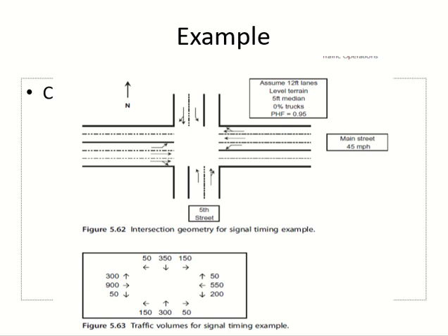The thing I was mentioning was that in this example there are no shoulders. If I say there is a shoulder as well, you have to add that one too. The shoulder will be on the road. So you have to look from one side to the other side, how many lanes you have, median, shoulder, everything, and add it. Clear? This is your W. This is how you get W. And you can see each direction has a different W.